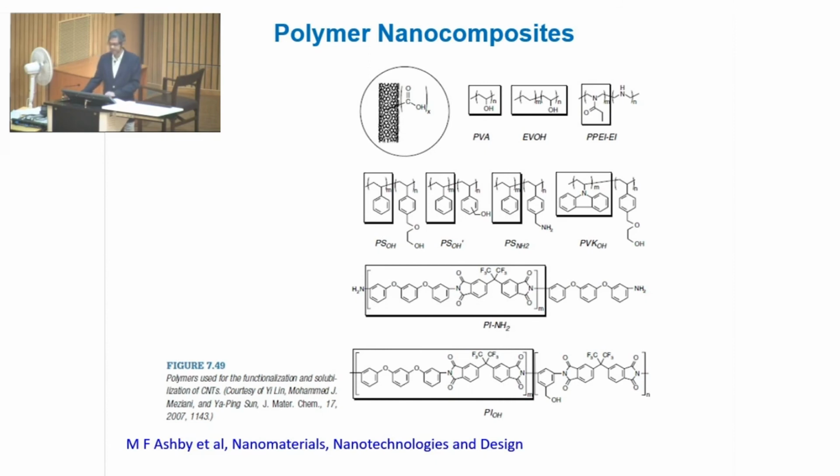So, in addition to uniform dispersion in the polymer matrix, a crucial aspect for providing optimum properties in the polymer is orientation of the CNTs. Because of the very high aspect ratio, CNTs possess highly anisotropic mechanical properties. To take advantage of their load carrying efficiency along the axial direction, it is essential that CNTs are well aligned within the matrix. Several methods have been used to do that.